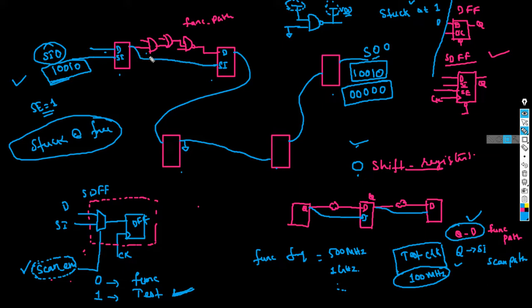Probably you won't understand at this point of time. You will understand when I get into something called STA and power analysis. So remember, your overall power consumption is alpha C V squared F. That is going to be today's topic.